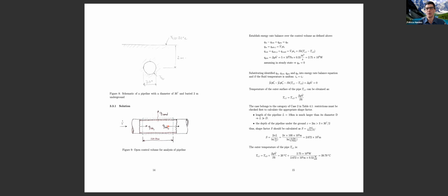And what we saw is that for pretty much any normal pipe, if you calculate the Peclet number, which I'm not doing here because I know it all too well for the case of pipelines, you get that the Peclet number is enormous. And an enormous Peclet number means longitudinally it is completely dominated by advection. And that's why we didn't include conduction in the longitudinal direction.